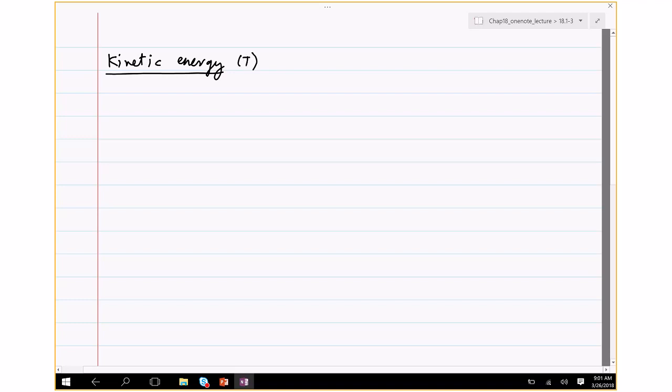Okay, so central to evaluating velocities and positions using this method is to find the kinetic energy. Now, the kinetic energy for a particle is half mv square, right? Turns out for pure translation, that's true. So if the body is translating but not rotating, then you can apply the same formula to find the kinetic energy. It's half m vG square.